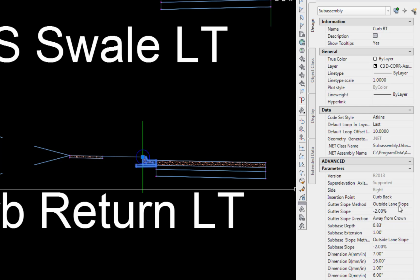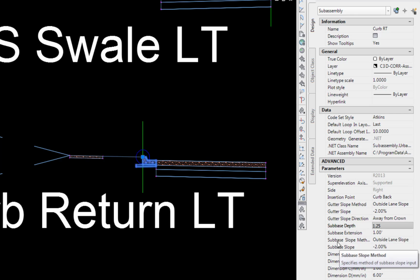Gutter slope method, outside lane slope, -2%, gutter slope direction away from curb, subbase depth, 1.25 feet, subbase extension, 1 foot, subbase slope method, outside lane slope, subbase slope, -2%, dimension A, 8 inches, dimension B, 1 inch, dimension C, 0.1 inch, dimension D, E, and F remain as is. Dimension G is 14 inches.